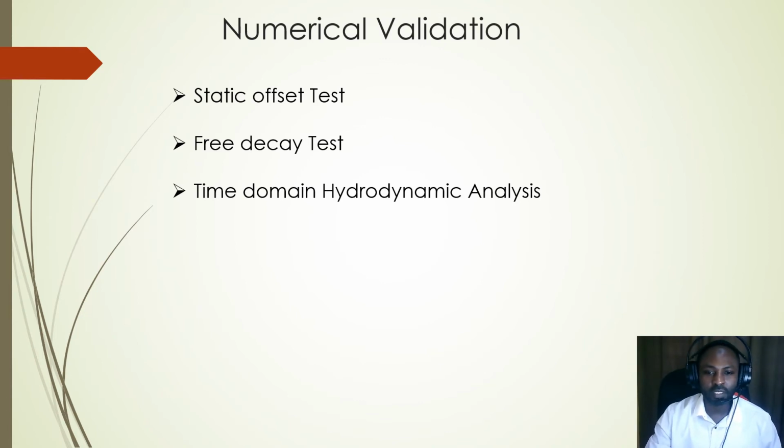Then the free decay test was conducted to determine the natural period and corresponding damping ratio of the FPSO. Then time domain analysis was conducted to determine the 6 degrees of freedom of the FPSO and the corresponding line tension. So the aim of the validation is to try and achieve as close as possible the published results.